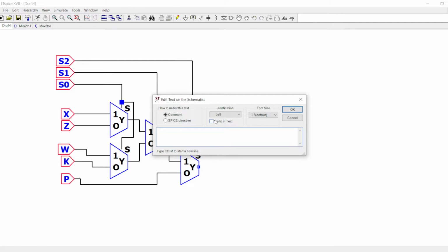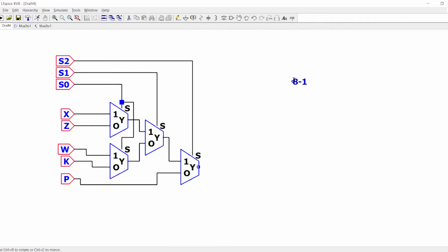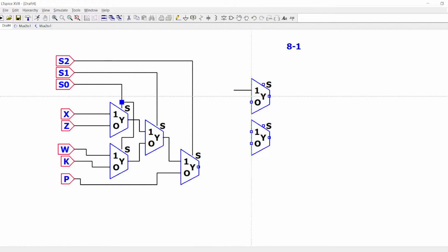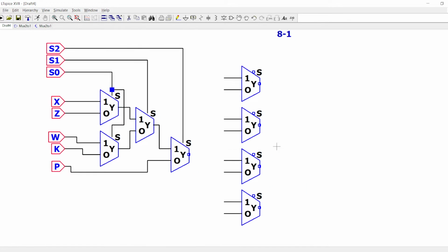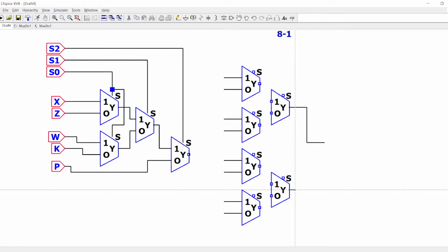If you wanted to do an 8-to-1 multiplexer, for instance, the result is the same, okay? You have always to take as many multiplexers as you can at the input. So you have 8 inputs in this case. So again, like this. Then for each two outputs, you put a multiplexer, like this. And since you have other two outputs here, you use another multiplexer, like this.